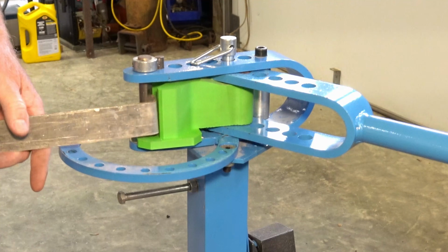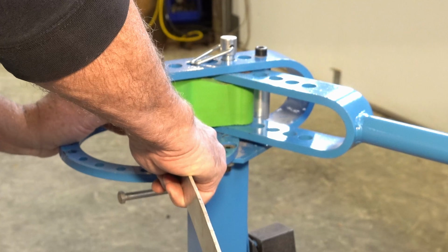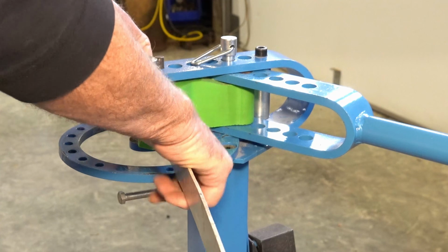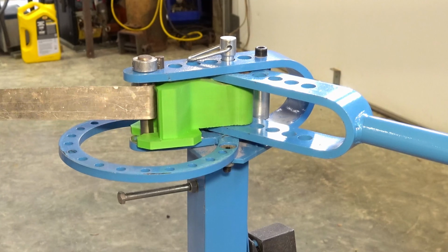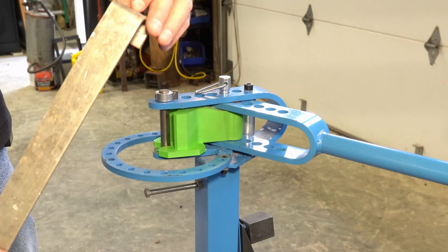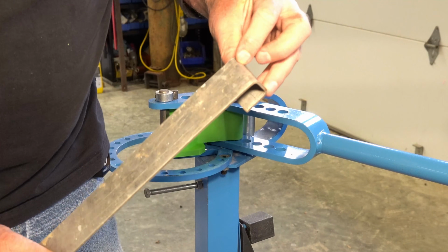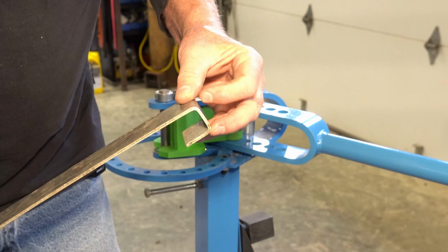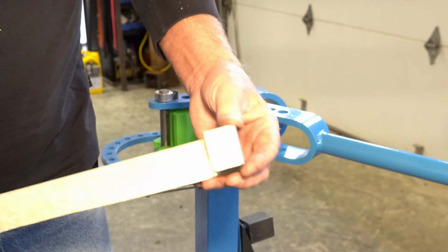Let's see if we can make another bend back to back. I just need to fix my dimensions on my model, but once I fix those dimensions, I think I'll have myself a nice bender down to horseshoe. I'm pretty sure this is 5052 aluminum because I'm not getting as much cracking. I'm getting real light cracking on this edge. If it's 6061, it's harder. It's going to usually crack on you, but that bent pretty nice.